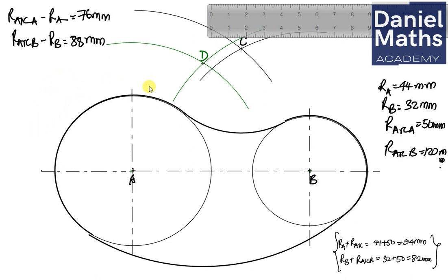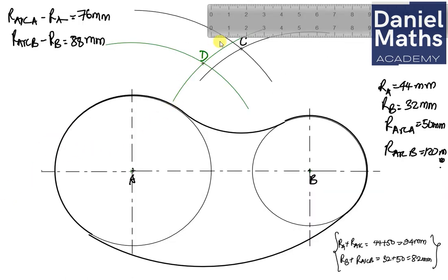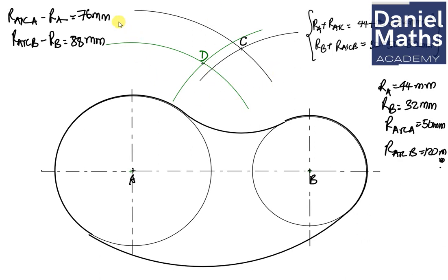Okay, now to you guys using how to produce this same question that we had here. So now we've shown our centers. These are centers. This point C and D are centers we used to construct our arc. Alright, so I don't need this again. So all of this is gone. What is left for me now to do is to begin my dimensioning. So let me do this with my tip pen. All right, so I have my dimensions.